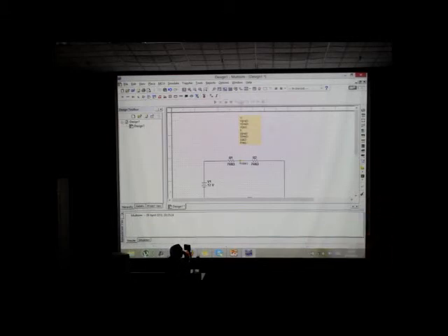So if you want to get values here, you just click the play button, and it gives the voltage. Since it's a DC, it's not varying. You can see on the top there is a V of 6V, and the current is 7.81 mA, and IDC is 7.81 mA. You can see these two resistors are identical, 768 and 768. The voltage here is 6V, and the source is 12V. So basically it divides into two because they are identical resistors. It's pretty understandable that this is working.